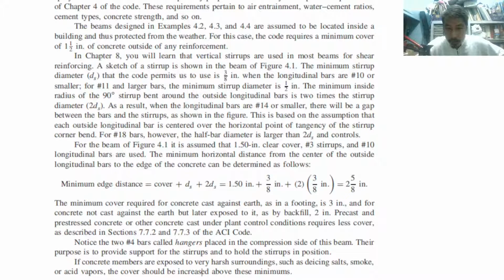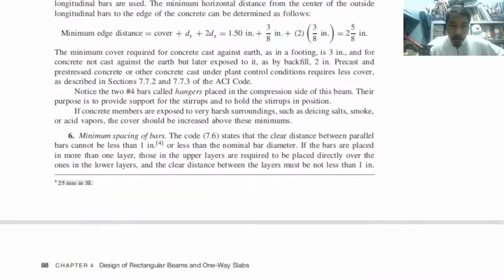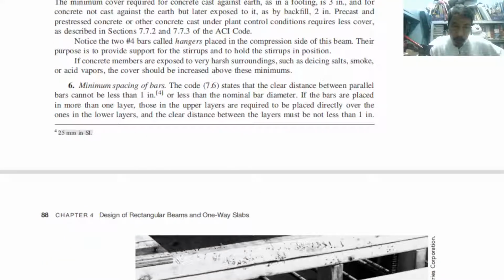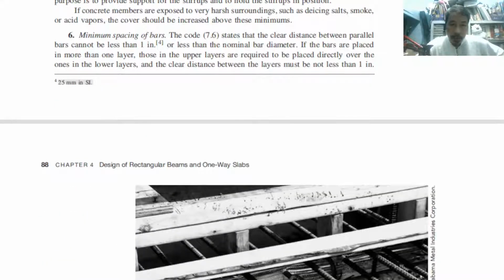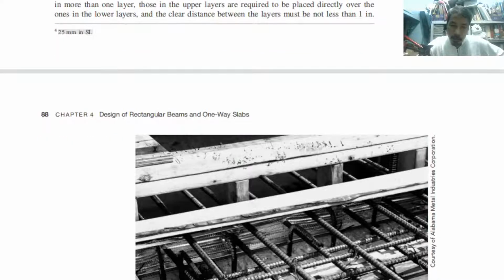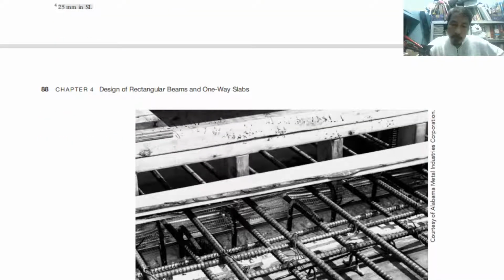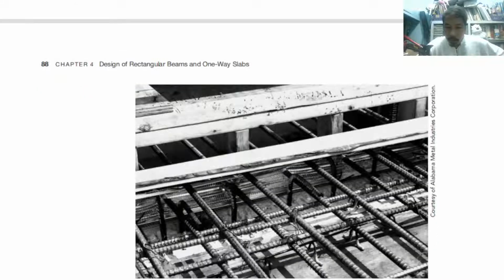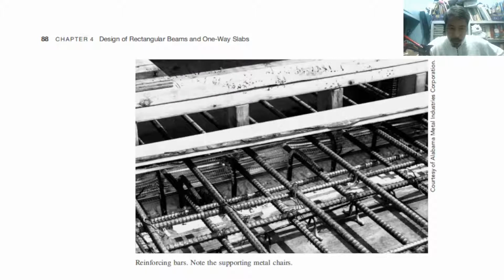That's why we need to have the minimum spacing and have the placement of upper layers of reinforcement on the same vertical line as the lower reinforcement.